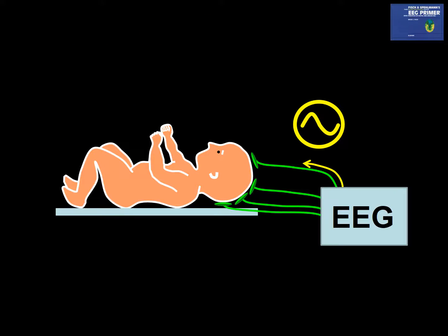Electrode impedance is measured by passing a weak alternating current from the electrode selected for testing to the patient's scalp. The electricity from the EEG machine impedance meter goes into the selected electrode, spreads in the scalp, and returns through all other electrodes connecting the patient to the EEG machine.